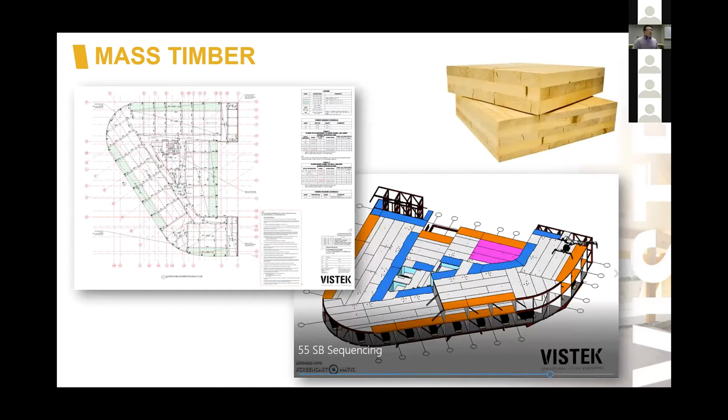Most of my talk will probably revolve more around the mass timber side of the discussion. This is a 55 South Bank floor plate, supported on a series of CLT walls. This behaves relatively rigidly, but really CLT itself is more likely to behave as a semi-rigid element, somewhere between a flexible element and a rigid element.